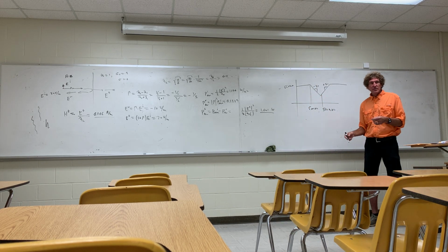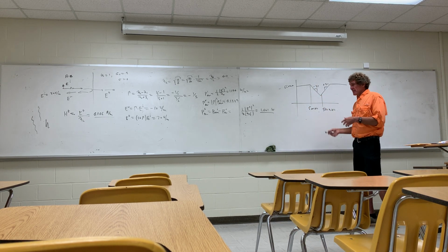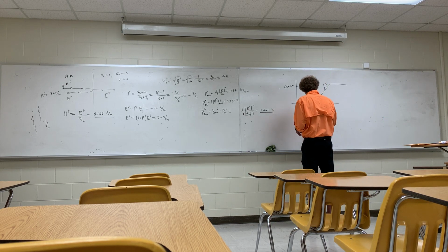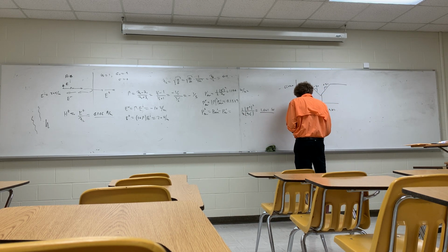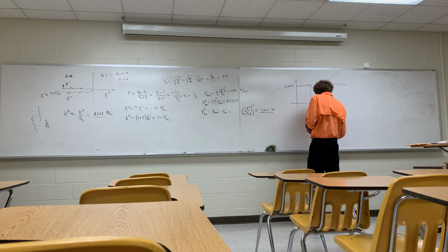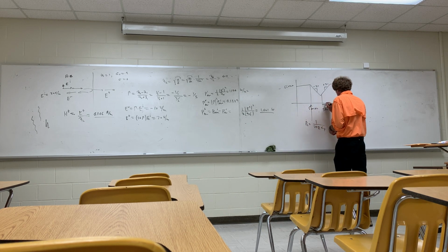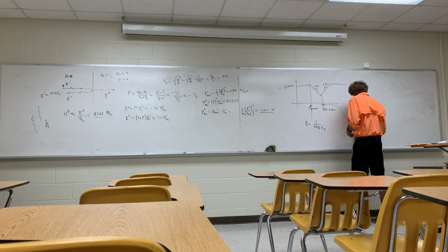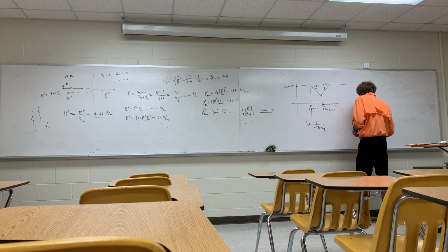The only thing you have to do, you remember this in class: this frequency is the lower cutoff frequency, and that's equal to 1 over 2 pi R times C, and that would be the parasitic capacitance. This frequency right there is the resonance frequency, or self-resonance, and that's equal to 1 over 2 pi square root of L times C parasitic. This is L in the leads times C parasitic.